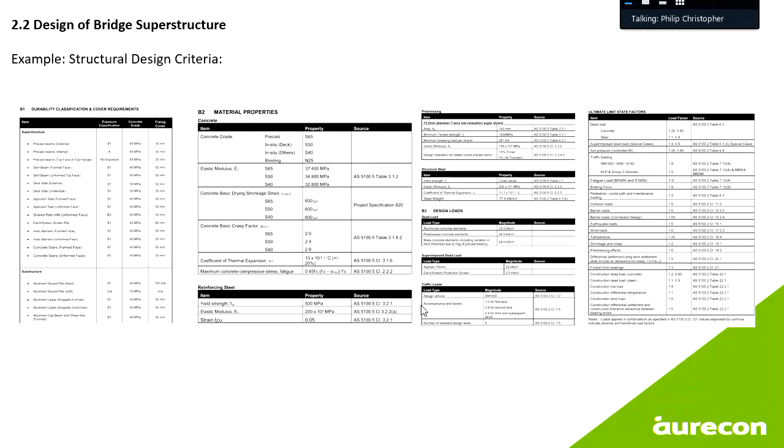Typically for a structural package, as a designer, you will then prepare a list of the design assumptions to enable any reviewer or independent verifier to assess your design. Because you will get about 3 or 4 times longer than the reviewer, you get to do a bit of decision making, optioneering. So by the time the reviewer receives your package, they need to know what kind of design assumptions you have made. Instead of trying to do a complete independent verification, they get to know what assumptions you have, and then they will make their sound judgment based on this.